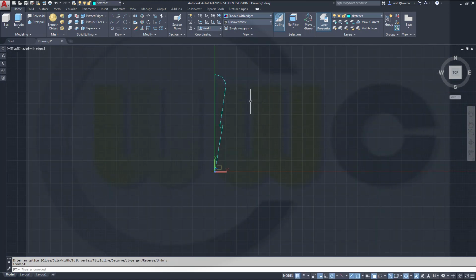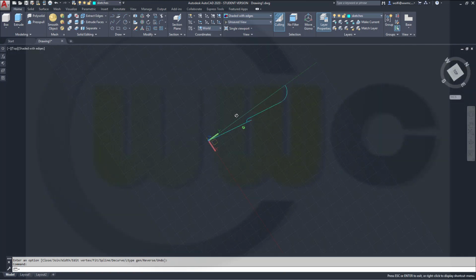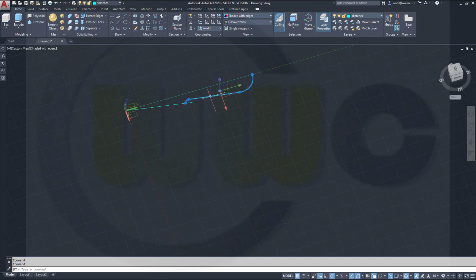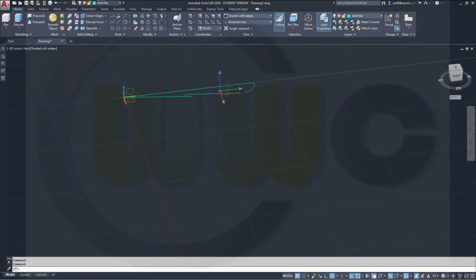And I need an extrude, and I want to move that, so I should maybe first move that polyline. So just activate the gizmo, yes, if you select it like this, the gizmo will show up, and I want to move that in that direction by 300 and let's say 300 in that direction.